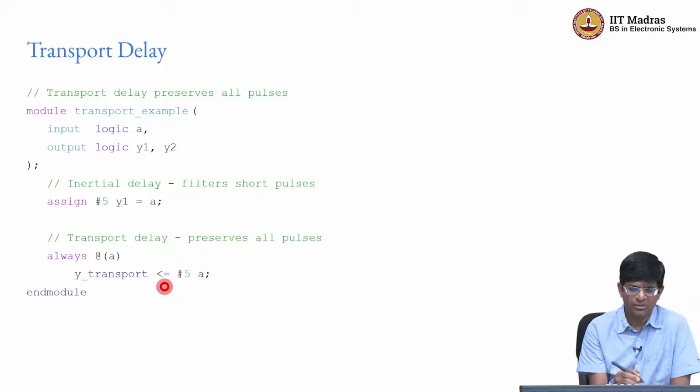But for now, the important point is that whenever you find that you need to model something like this, it's very rarely a good idea in practice unless you have sufficient experience with Verilog that you know exactly why you need to do this. So, at least at the beginning stages of Verilog, this is not really something to be concerned about at all. You should not be writing code like this. And as we will see later, as a general rule of thumb, when you have something like this, you are sort of trying to model combinational logic, and non-blocking assignments and combinational logic do not go well together.